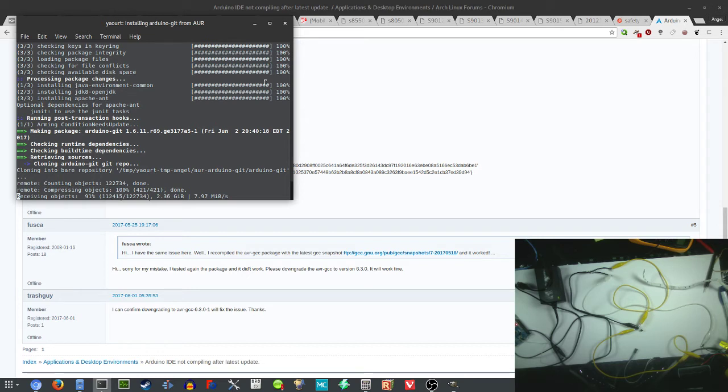So it's not gonna float like this because it's gonna have the same ground as the Arduino. And then I'm gonna put 12 volts from the power supply, and 5 volts are gonna come from the pin of the Arduino. So hopefully it doesn't float like that, where a slight bit of current can... like as long as it's not completely floating like this, it's gonna... which is not good.